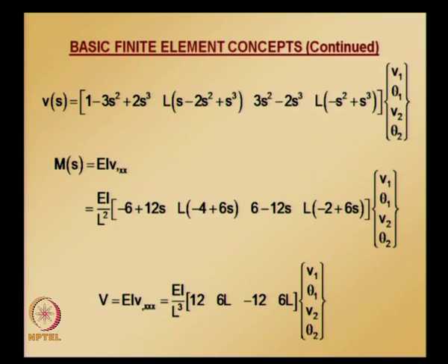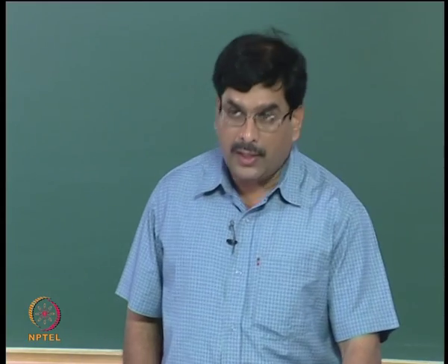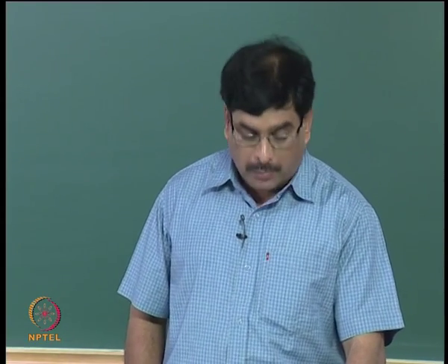Therefore, analysis of continuous beams in which cross sectional properties do not change in a span requires nodes only at the supports and under the concentrated loads, whereas non-uniform beams, for which EI is not constant throughout the length of the beam, require more elements per span for better accuracy. These are things we need to keep in mind when solving problems related to beam bending using the finite element method.